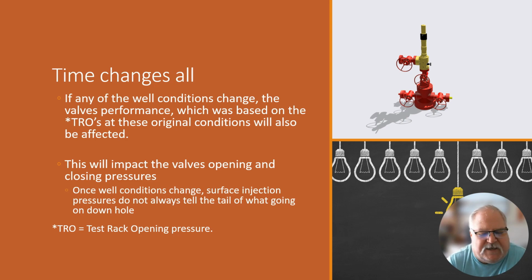You change any of the pressures in the tubing at that point, any pressures in the casing, all those things can have different impacts on when the valves actually respond. Probably one of the biggest things is, of course, liquid volumes are decreasing and temperatures are changing in that midpoint of the well, and usually you see a pretty wide swing in the test rack opening pressure of that valve because of that temperature change.